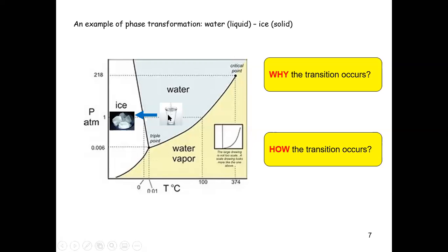Because that is the way we process a material system. In most cases, what we do in the processing is that we do not change the pressure. The pressure will be kept at atmospheric pressure, and we change the temperature. We cool the system in different ways, either fast or very slowly, so that we can introduce the liquid-solid transformation at different rates to achieve different microstructures. So that's basically the phase transformation and how we can induce phase transformation in the material system of interest.